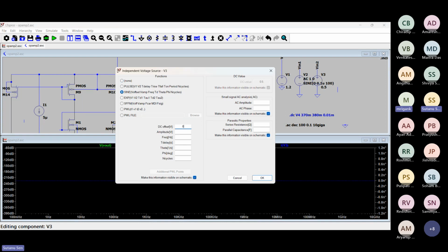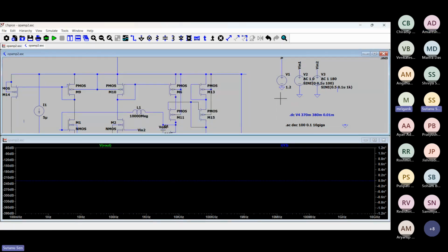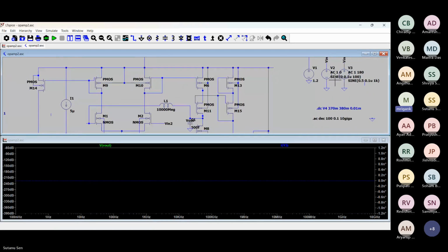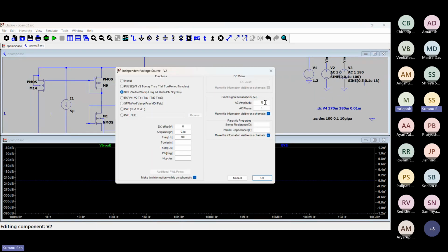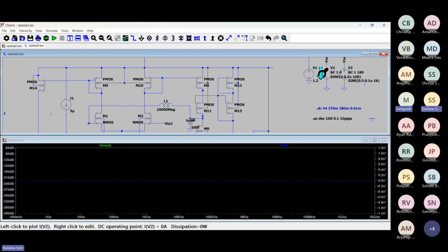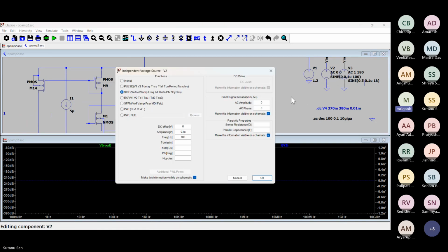This is just a trick. Generally we don't use this in Cadence, but in this particular tool that feature is not there, that's why we are using it. The open loop analysis, the way you are doing right now, requires an STB, a DC point calculation. First you find the appropriate input DC level so that the output is at the midpoint, and then do the AC analysis. But using this approach, you're not getting that.